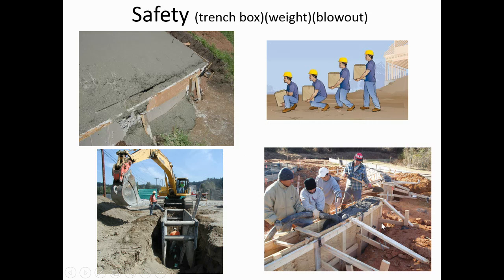All right, safety. Concrete weighs a lot. Those bags that we're going to be using weigh 80 pounds apiece, so you've got to be careful when you're lifting concrete. The top right-hand picture shows to lift with your legs and not with your back. When you're building molds or forms, you have to be really careful that they're strong enough so they don't blow out while you're pouring the concrete. Up here in the top left-hand side, you can see a mold that's starting to fail. The concrete is coming out the bottom, and this is going to be a big mess for somebody.